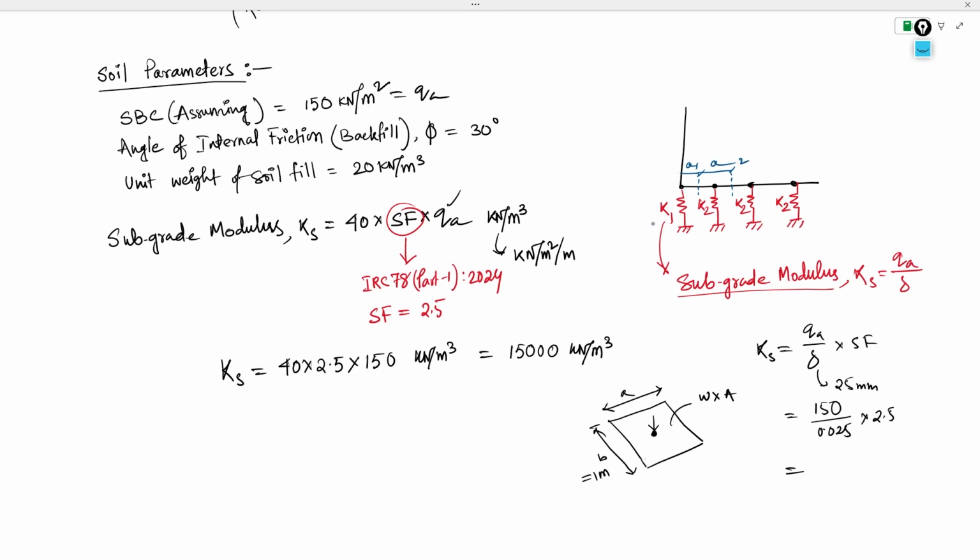That's why I have named them differently, because the corner nodes will have a smaller tributary area as they don't have the other side. But the internal ones have both sides, so the tributary width will be half of this side and half of that side. That means it will be similar to the node to node distance for the internal one.